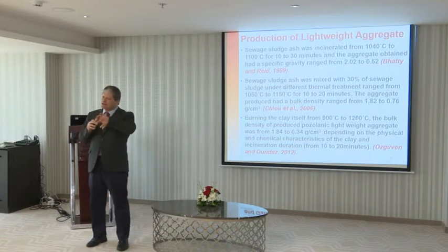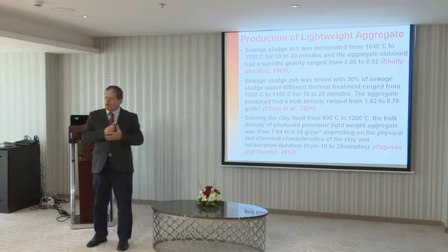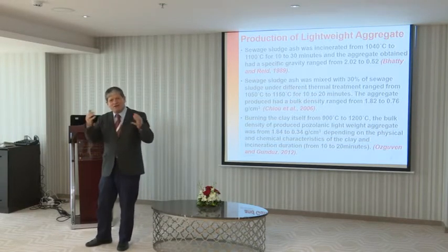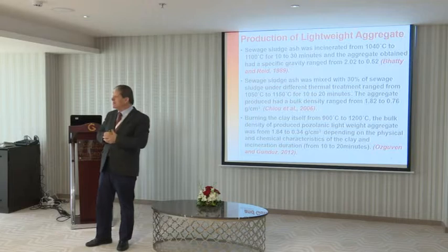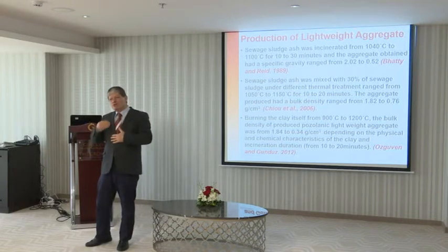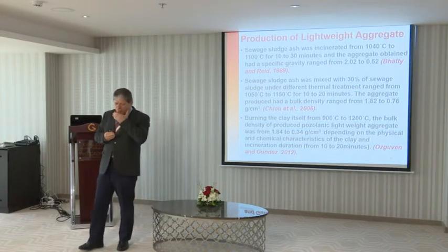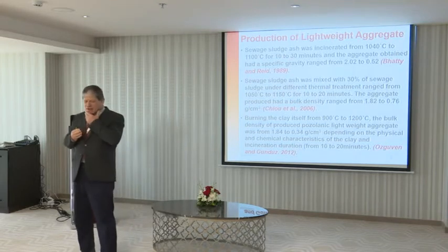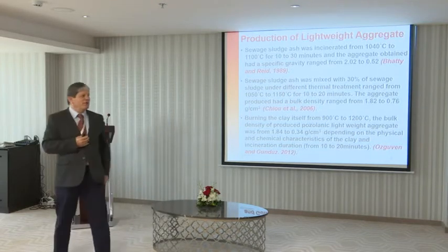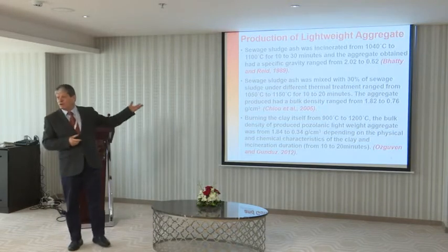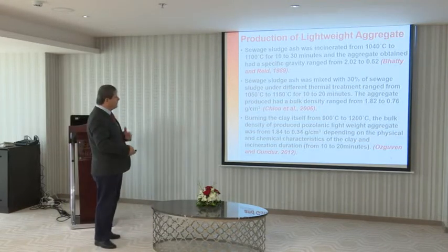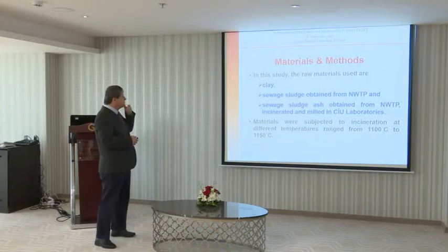So we can get rid of this calcium hydroxide, or reduce its amount by half. If you use pozzolans, that is, silica in it, they can react and some cementing material is produced: more calcium silicates, less calcium hydroxide. So using reactive pozzolanic materials in cement production is very useful. That was actually the target of what we are trying to do.